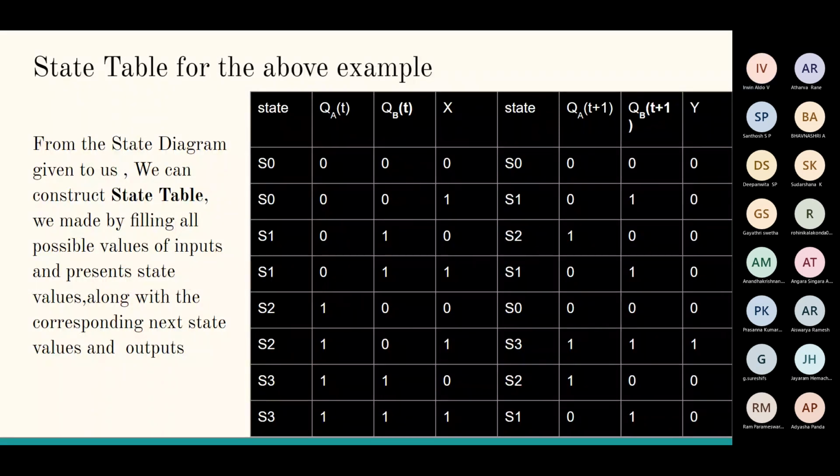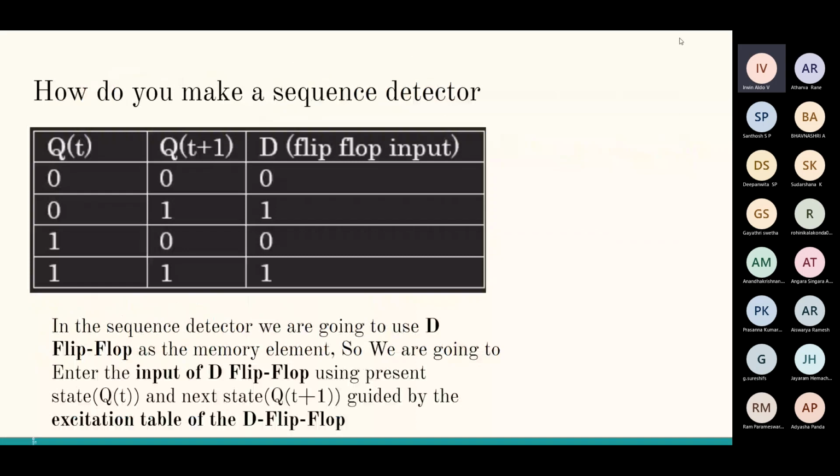Okay. Now we have considered every case and successfully built our state table. I think you guys can remember this table from the last session. This table is nothing but the excitation table for the D flip-flop. Since you are familiar with the D flip-flop, as in the last two sessions we built two examples with them, and we need two flip-flops for this state diagram, for this sequential circuit, I'm using D flip-flops for our problem. So first I'm writing the excitation table for the D flip-flop.